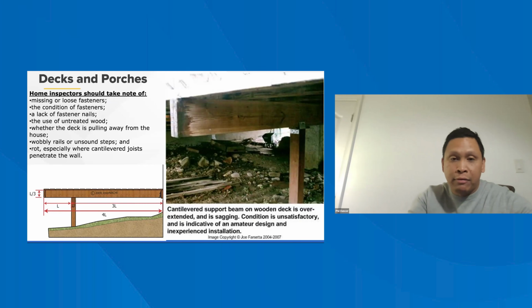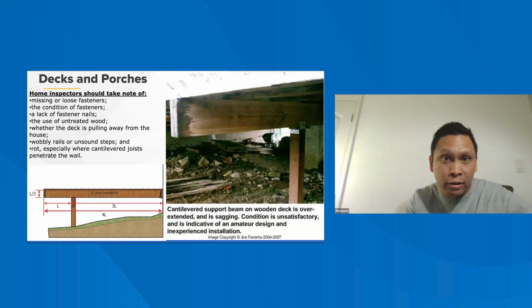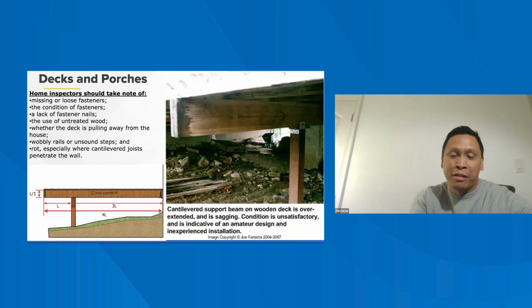I've seen it periodically over the years where the subcontractor will literally attach the ledger board to the house, bolt it through the ledger board onto the OSB sheathing, but then nothing else. And then when you go inside the house, you'll actually see the other end of the bolt, and it's not going into framing.